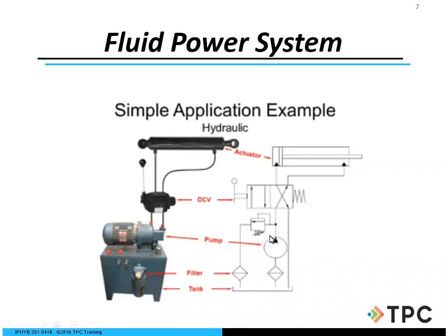But as we see here, as we have our pump, we go into a pressure relief valve here. And so once that pressure has been reached at a certain point, yes, we will have our fluid running back to the tank. So this is part of our return filter, right? And so this is the filter that's coming up, filtering the oil, critically important. Contamination, like I said before, is number one with hydraulics, let alone the misalignment part.